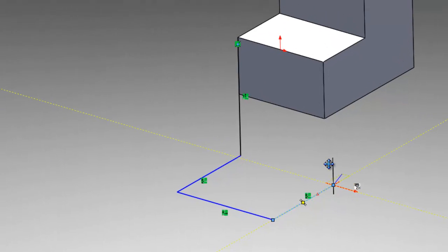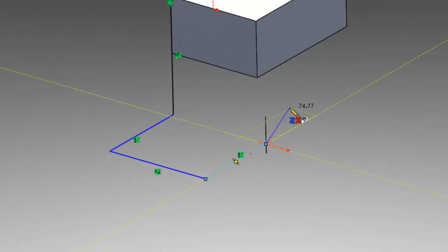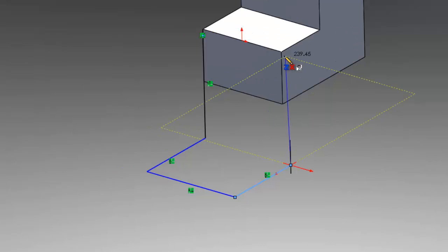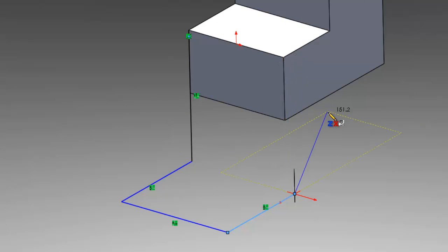Now, just so you guys can see this in the YZ plane, but notice if I float my cursor over other geometry, I can actually draw to that entity. So again, just because it says I'm working in the ZX direction doesn't mean I'm constrained to that. I'm just trying to drive that point home because I think that's a thing that confuses a lot of folks. Just because it says it's working in the ZX plane doesn't mean that it works exclusively in that plane. So you can actually select other entities, and you can see with the yellow inference lines here that it's actually traversing a volume to get to this point.